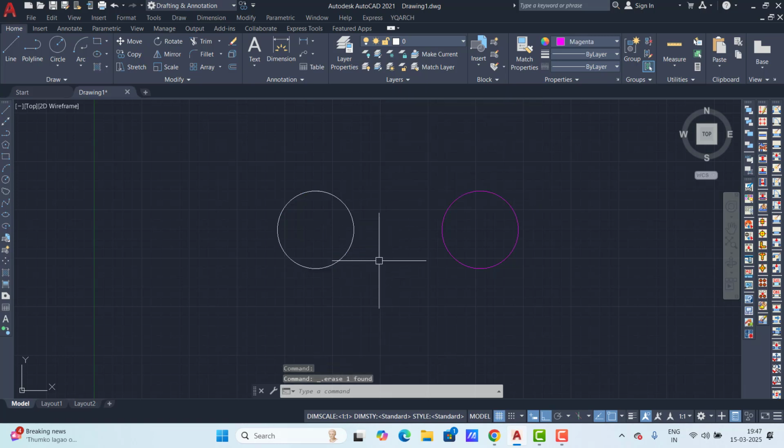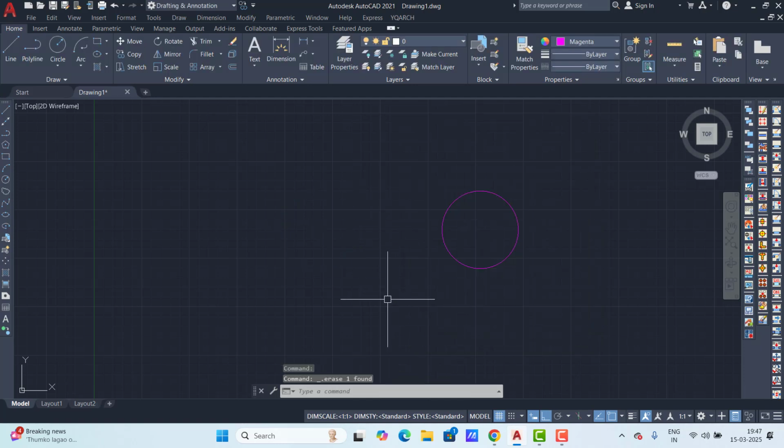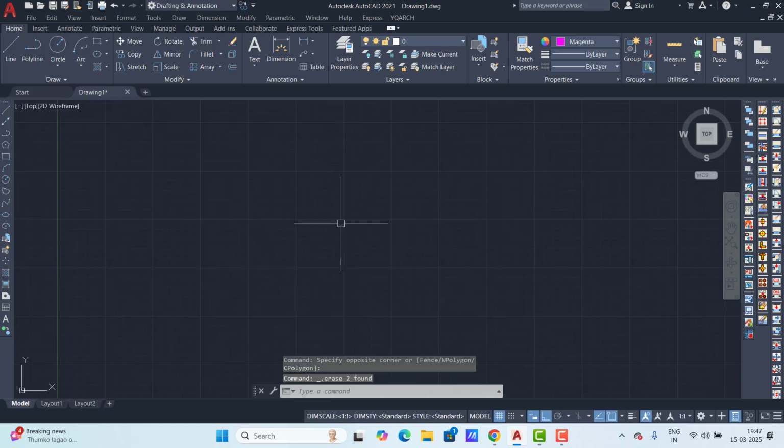So just select this pattern, and in this situation you just deactivate this one. When you apply the pattern, this dialog box opens automatically. Okay. Now just go and change this option here, deselect this option, and finish. When I select this line and drag, you see the pattern does not increase. If you want it to increase, just click and drag this way. So this is associative and non-associative. Whichever way you like, you can choose the option.